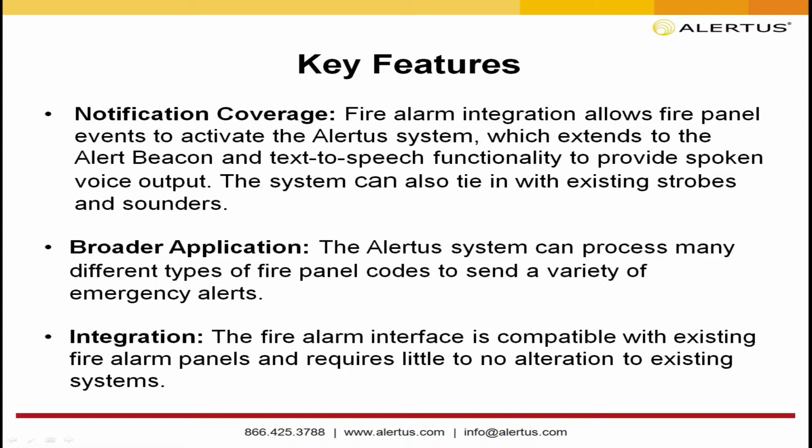Those speakers are something you guys have already paid for, you guys have already distributed throughout your facilities. So to be able to use them to distribute those mass notifications, all you would have to do is add in an extra wire, or I'm sorry, an extra 3 wires connected into your fire panel to be able to leverage those speakers from the Alertus system that you guys might use.